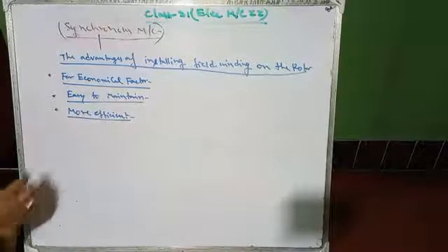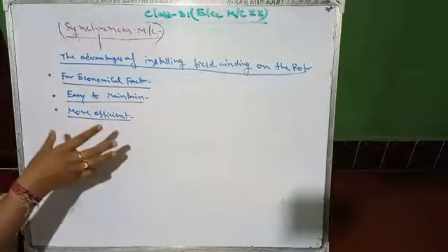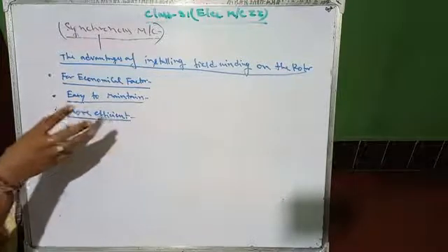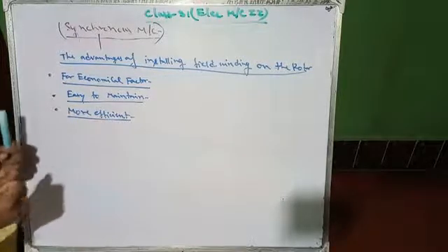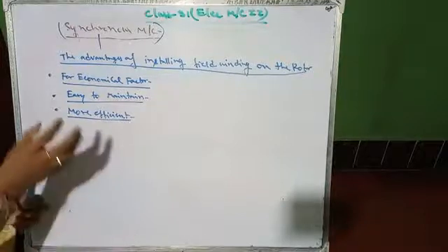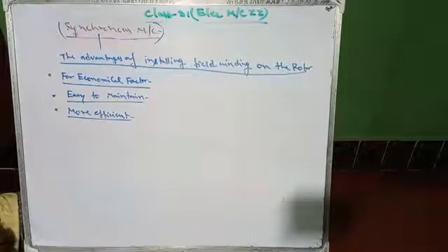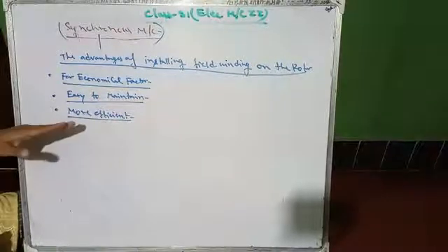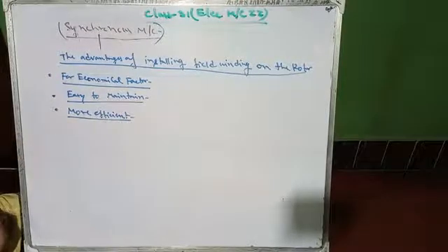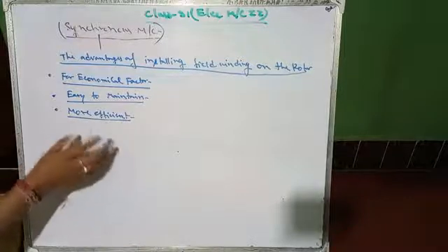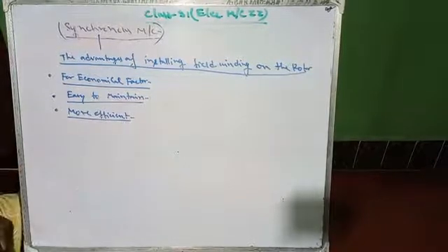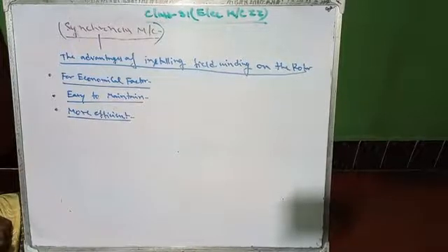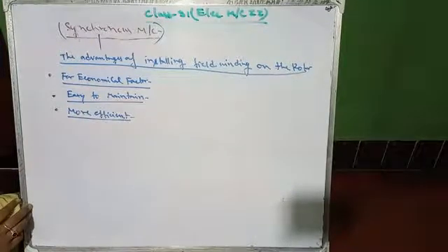So when the armature is placed in the rotor part, the collection system must consist of brushes and slip rings. There will be an I squared R loss at the brush and slip ring contacts, and also windage and friction loss.